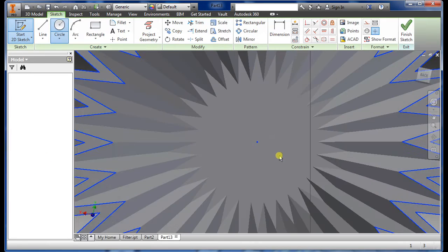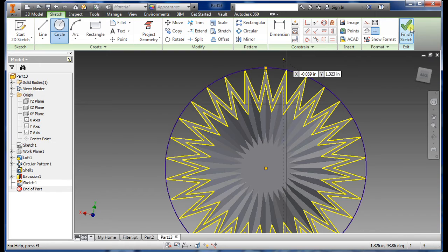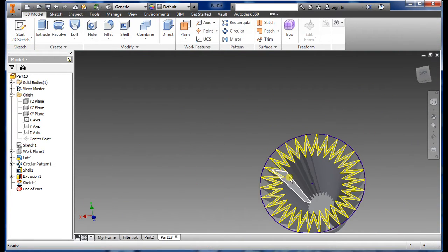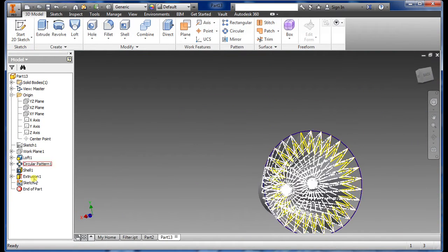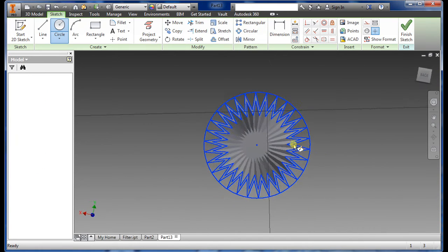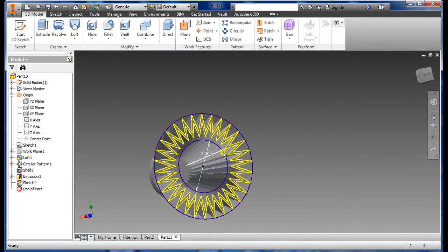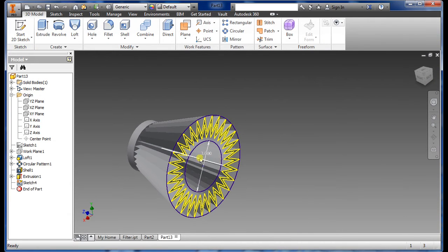And then now we're going to go down this side here. Select that. Go and select the circle. Go to the center until you see the green dot. Snapped. Another green up top. Hit OK. Actually, let me go back to the sketch. So go back into edit sketch. Draw another circle. I want 3-inch for this one. Say OK. That's how I wanted it. So this is how it's going to look.